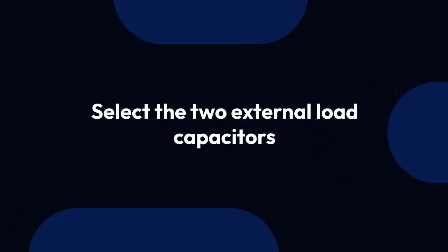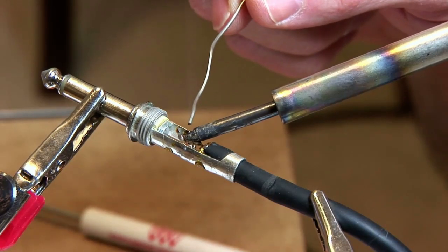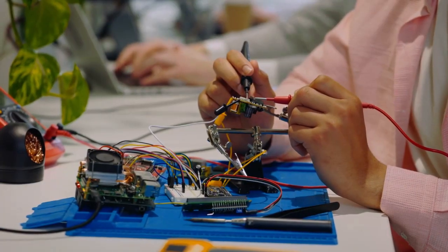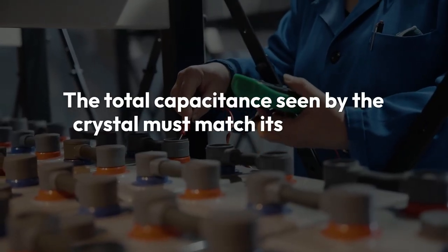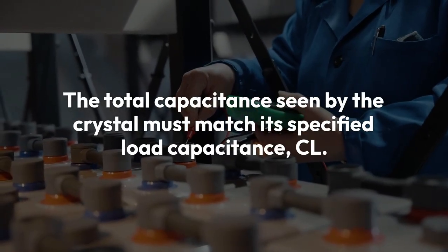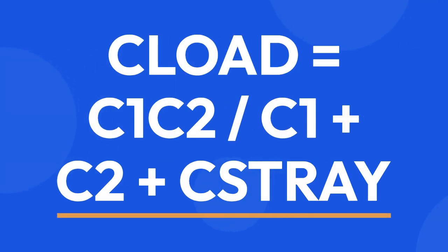Next, you will select the two external load capacitors. These are typically C1 and C2. They connect from each crystal pin to ground. The total capacitance seen by the crystal must match its specified load capacitance, CL. The formula for this is approximately C_load equals C1 × C2 / (C1 + C2) + C_stray.